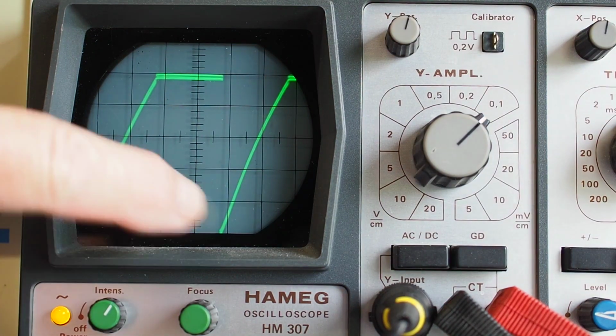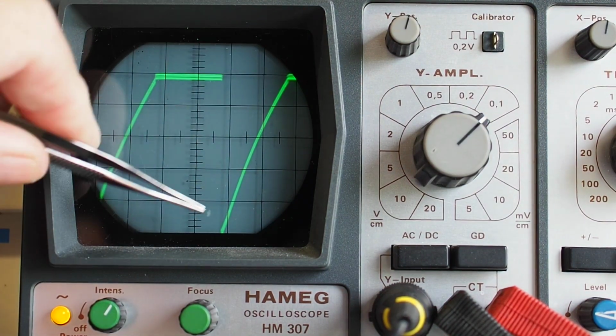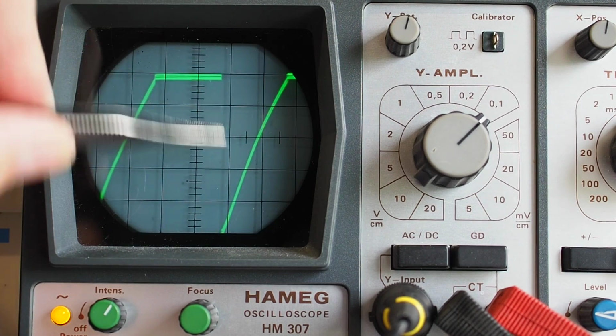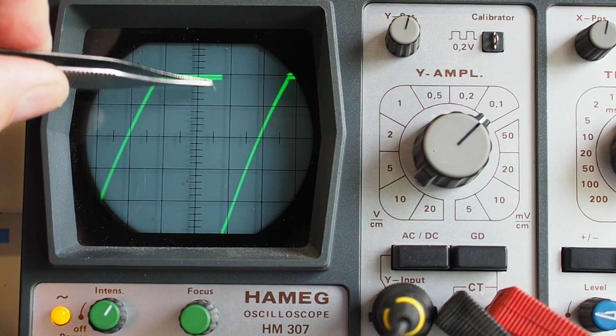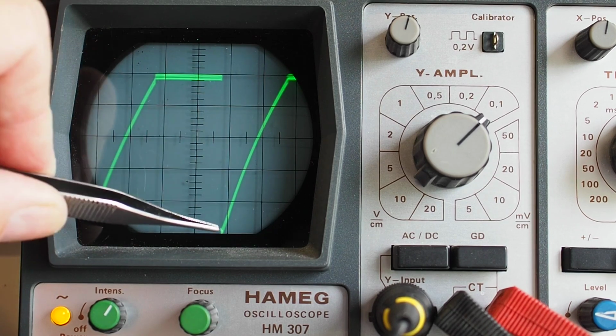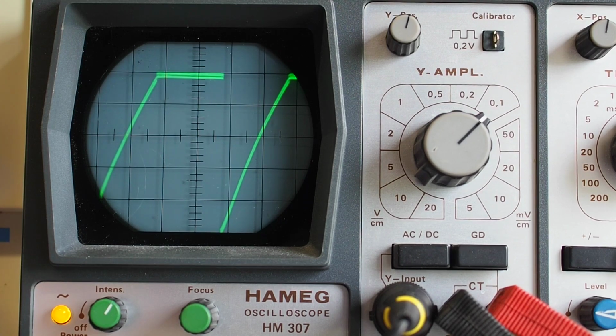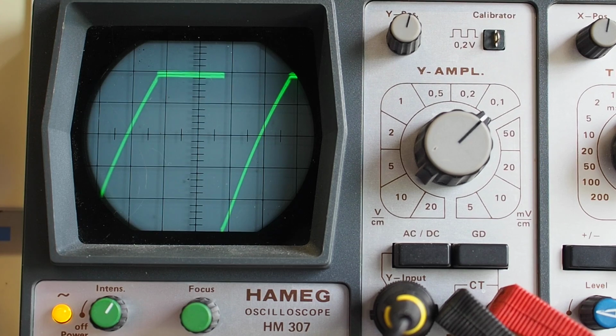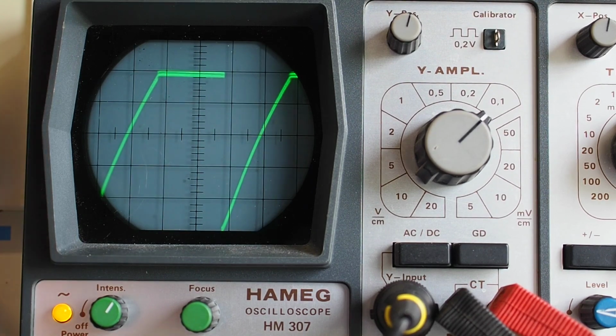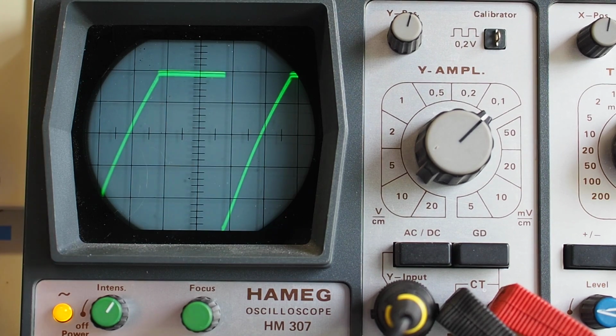Yeah, so there's the rising edge, which you can see fairly clearly, and you can't see any kind of falling edge there, and that's because the falling edge is so fast that the oscilloscope doesn't have time to display it. In other words, the bandwidth of the scope isn't sufficient to show the falling edge, so we couldn't, for instance, make a meaningful falling edge measurement of that, because the scope simply isn't fast enough to show it, even on the fastest time base.